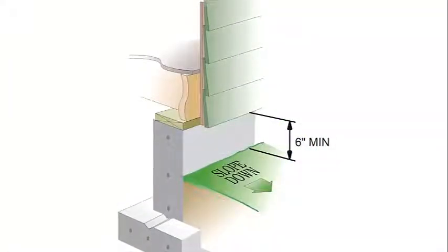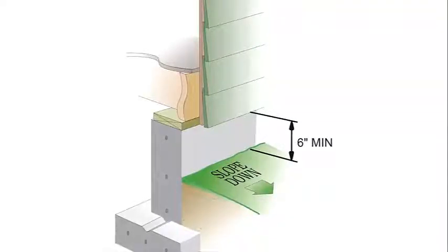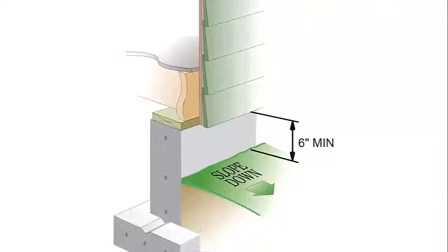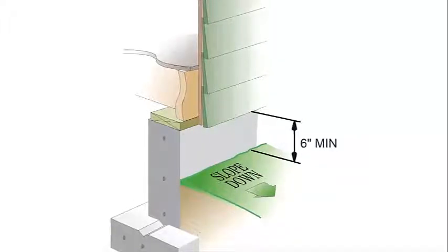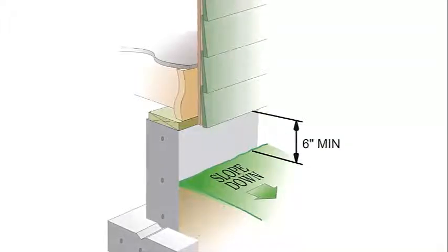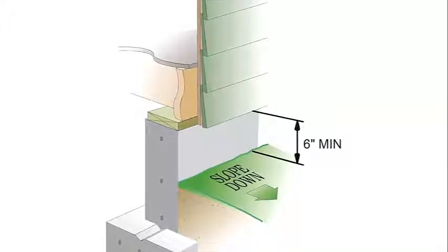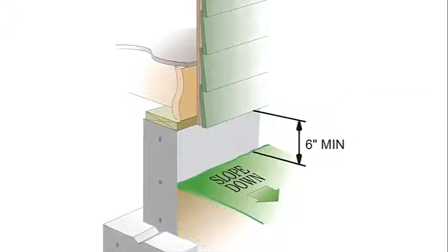If soil is brought up higher on the foundation wall in an attempt to remedy a slope problem, care should be taken to maintain at least 6 inches of clearance between the ground and the exterior wall material. Similarly, soil and landscaping materials, like mulch, should not cover brick veneer or the associated drain weeps if present.